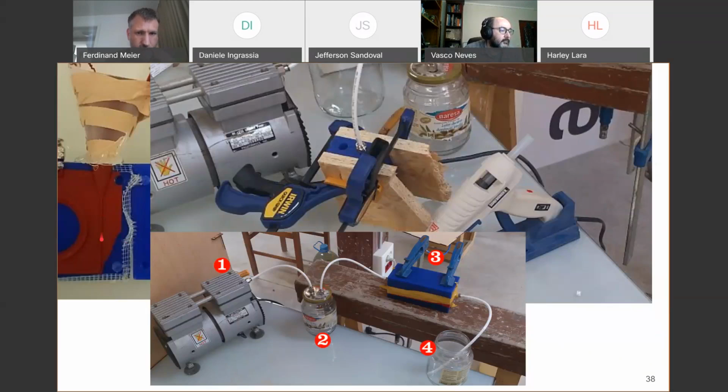such a thin area. So what they ended up doing is attaching pneumatic fittings to both sides of the mold and putting one side into the silicone and then sucking a vacuum on the other side. So the vacuum will pull up all your silicone, fill your mold, and then drop into what I would call a gate. So this one just prevents the silicone from going back into your vacuum pump. So this is actually a quite clever technique. We have lots of vacuum fittings. So if you're interested in something like this, let me know.